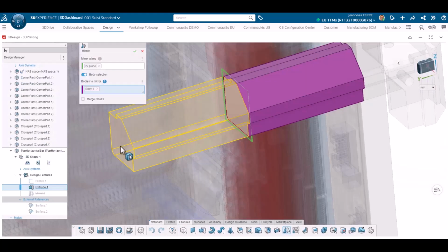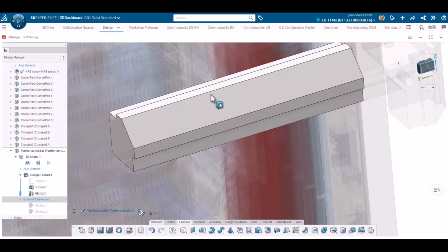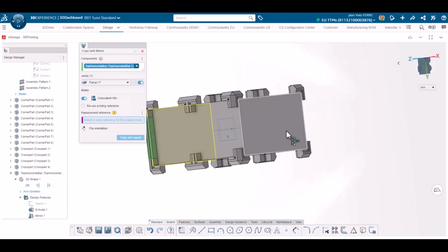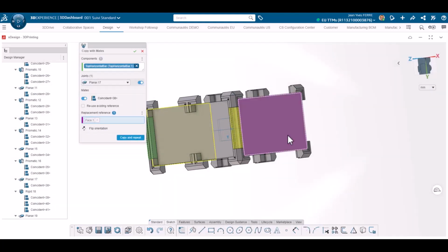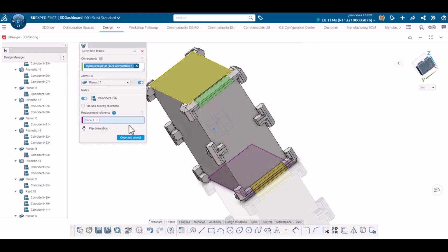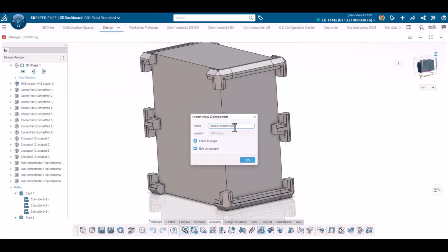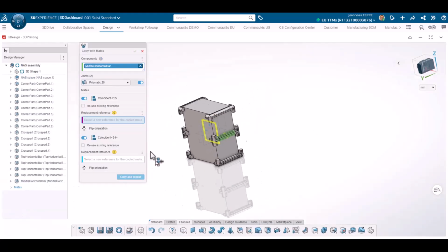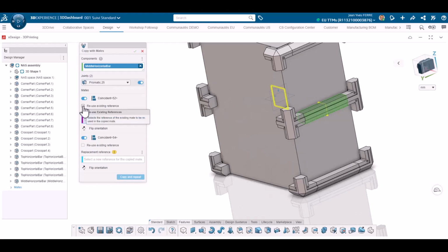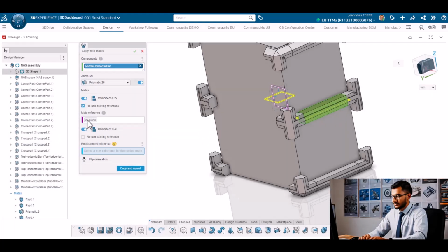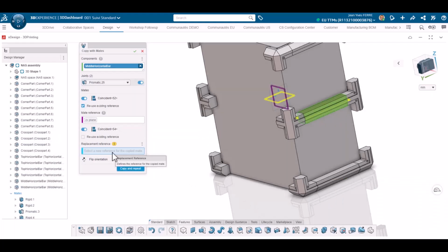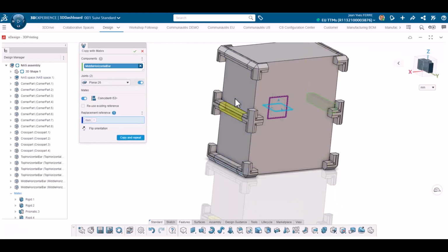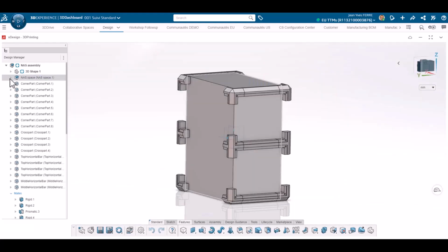Now that all joint parts are created and placed, I create bars but with up to reference so they will adapt if box changes sizes. For sketch, I leverage existing geometry to save time during this pre-design phase. Nothing is set in stone yet, so I don't spend time defining things that may change in the near future. Again, something that a designer would do in an industrial company. I copy the part with mates and start doing the exact same operation with middle bars on the side.